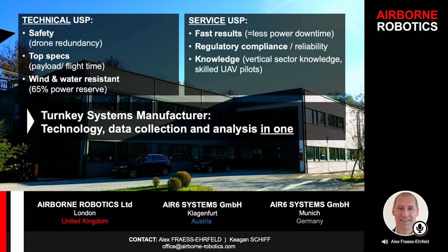Let me start with that and maybe hand over to Rob if you want to add something. So the typical Lidar system, which is used in the market, would have two returns. So that would be the first and the last return. So the first would be, as I said, the tree canopy, so the cover of the tree, so that you get the shape of the tree, for example. And then the second return would be the most solid one, which is the ground.